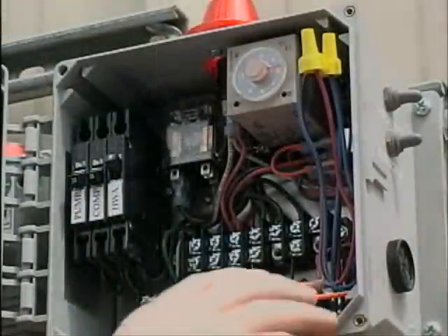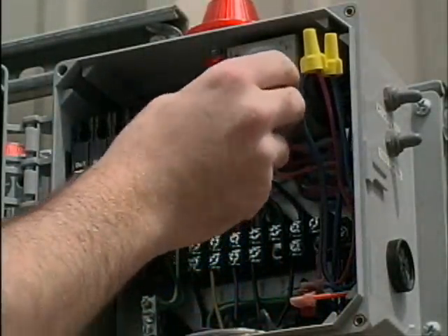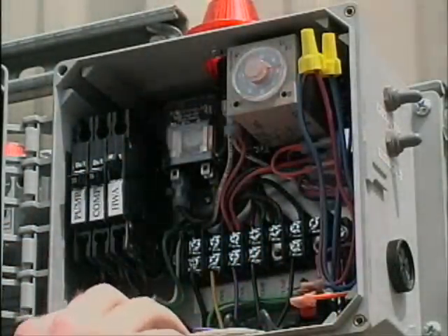The controller is another important piece. It controls the frequency and time of dose. If the dosing time is too long or the rest time between doses is too short, water may be forced to the soil surface. Therefore, dose and rest time must be matched to the site's soil conditions.